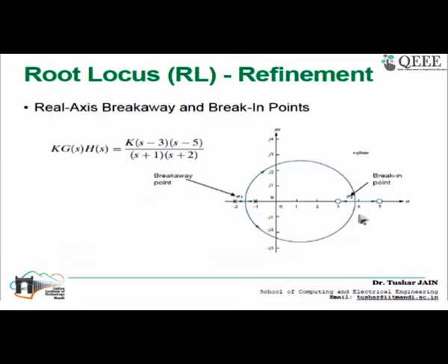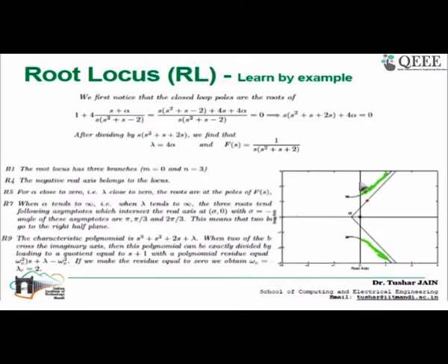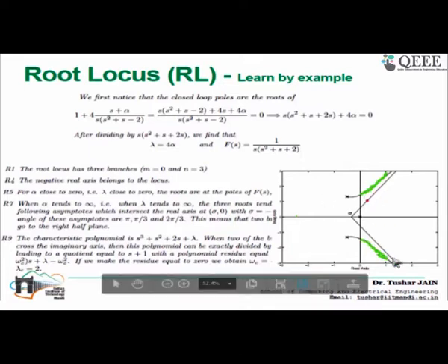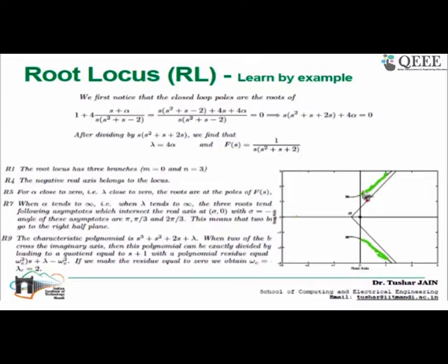So what you realize is, of all that you construct, first of all you analyze the stability, you construct the controller, and you also find out the range, that for what values of this alpha, which is a part of the controller or the pole, how the stability is changing. If you fall into this region, your system is unstable. If you strictly stay at this point, you are marginally stable. If you choose the value of alpha in such a way that you are always on the left hand side, then the system is stable.